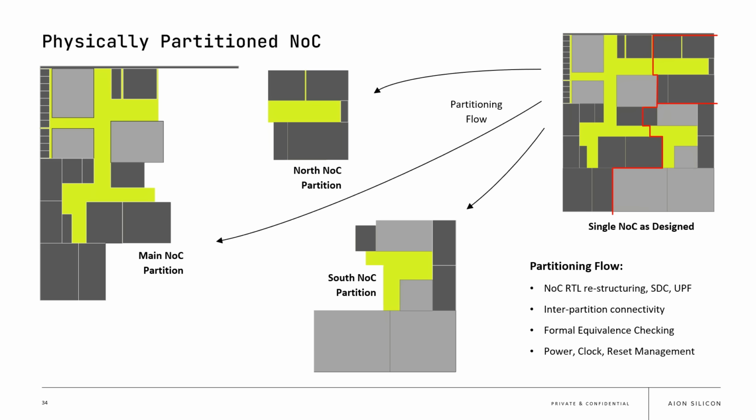So they'd prefer to harden those sections first. But it also helps with runtime. If you're going to have lots of turnaround, lots of churn, then having smaller sub blocks to take through the backend flow means you have a faster turnaround time.